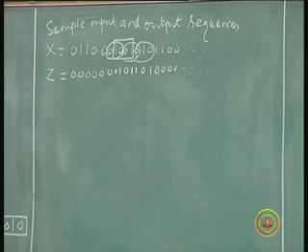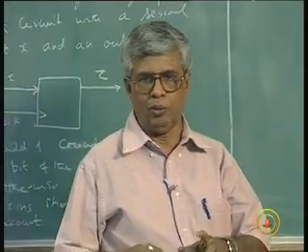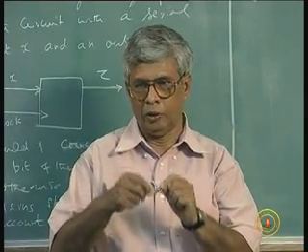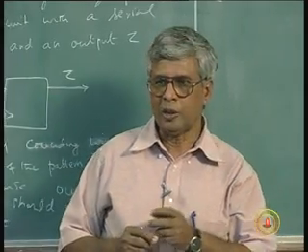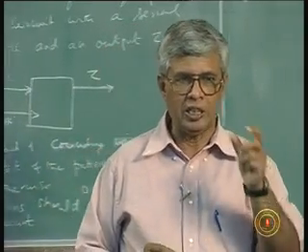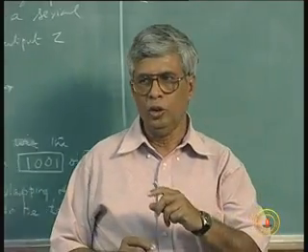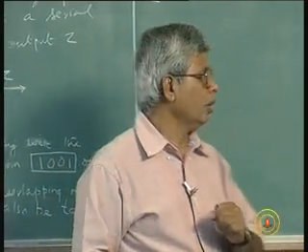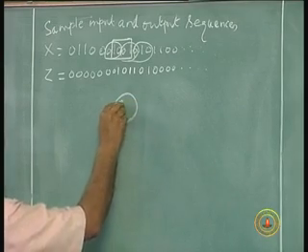Similar example to what we did in the last lecture, but slightly more involved in the sense there are two patterns, one is a larger pattern and then this overlapping is also there. So, we wanted a Mealy machine, that means for each arrow from each state we will have to look at the possibility of x being 1 and x being 0, we have to decide the next state and the output for each of those. So, let us start with always a 0 state or a reset state, call it S0.